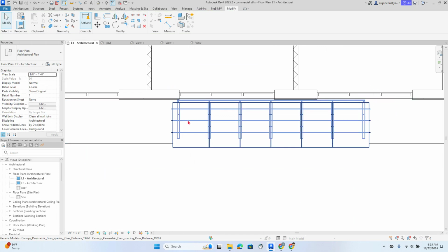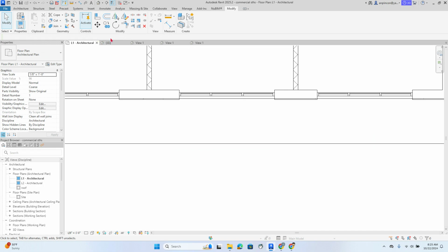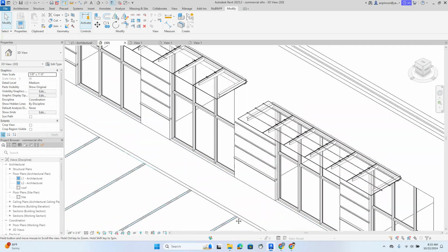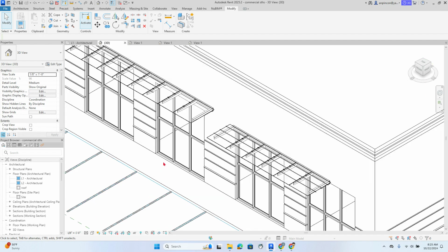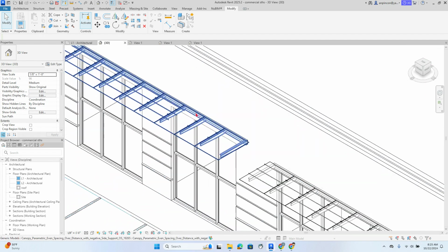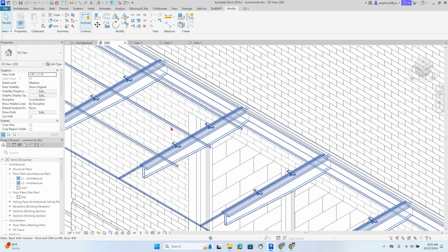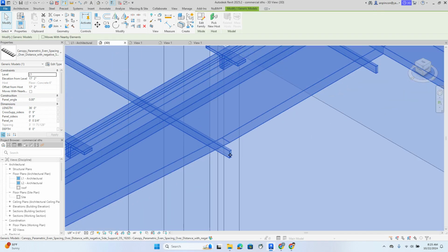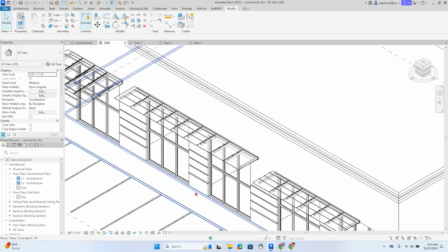Right here, I can right away go here, change the elevation for 16. So when I move to the 3D, it will go on the proper level, right? So this one is just a little bit different. Actually, I think I'm gonna delete it, and I need to modify. I need to find out what parameter is this one that is interrupting this beam to not go all the way here, or eliminate that one.